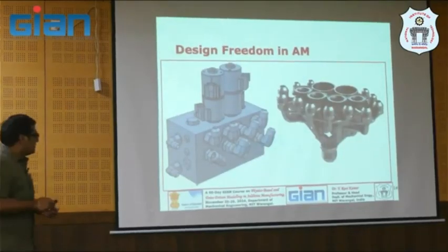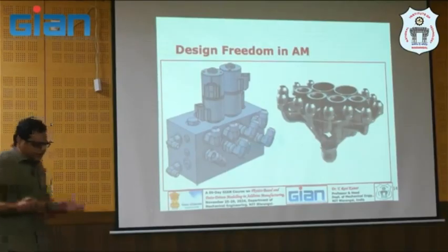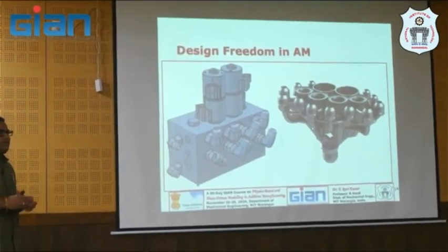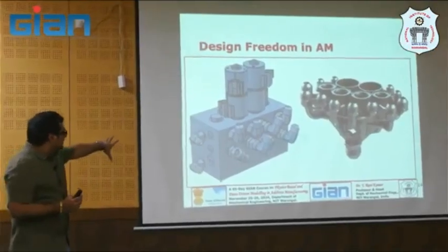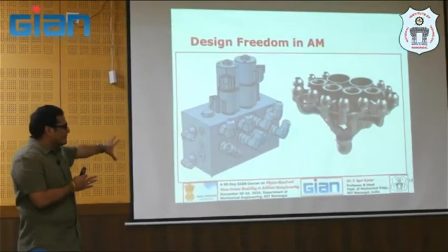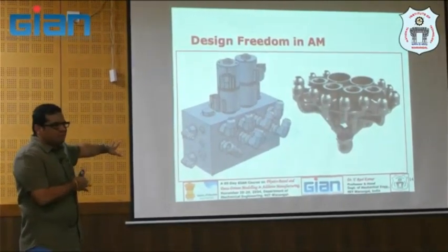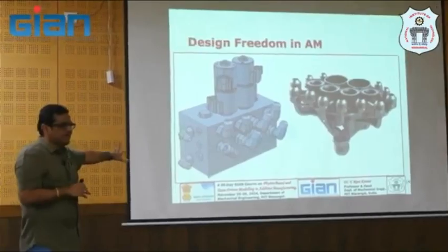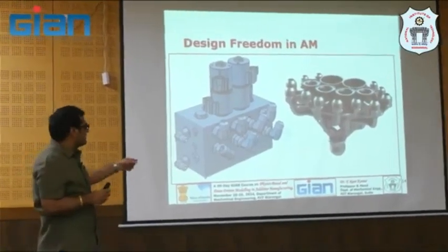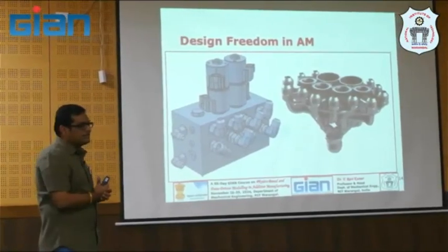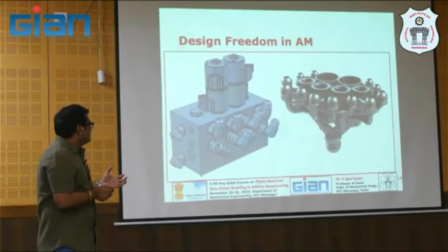Yeah, so if you see, your design freedom is such that your designer is not constrained by manufacturability. Again, you see the left side design and the right side design, where your designer might have compromised his innovation or his design based on the manufacturability of the component, maybe targeting a subtractive manufacturing process. But if you see the right side design, you can have better performance of the system, and you have a lot of design freedom